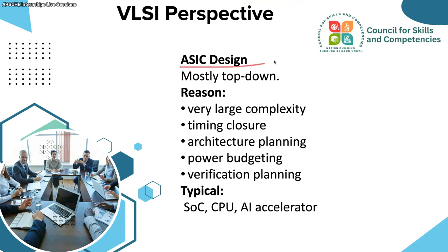So in application specific integrated circuits, mostly they will go for top down. The reasons are very large complexity, timing closure, architecture planning, power budgeting, and verification planning. Okay, these all favor top down. So SoCs, CPUs, AI accelerators, those are all ASIC designs. So they will go for top down.